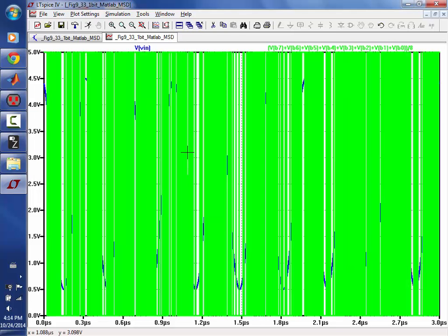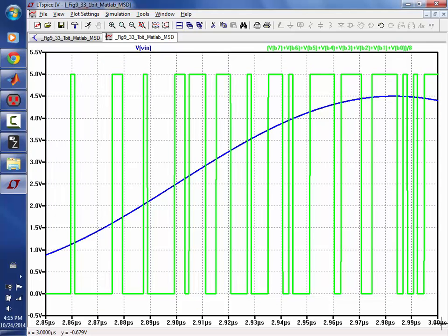Well, you assign them, and that's right, but the problem is if it goes in the pin table like 1, 2, 4, 5, and you don't have 3, it doesn't work. It just won't work if they're not continuous numbers. So I want to show you that.